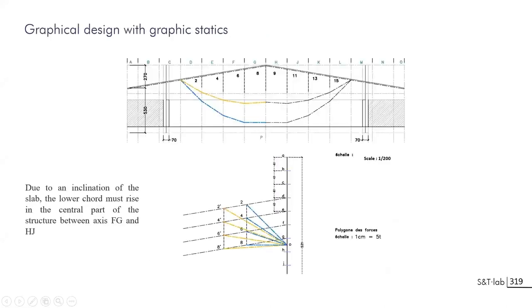So first you want to draw a funicular line. You would like to have a funicular line that would be horizontal in the middle. And if you do so, you have to keep in mind that this funicular line will be equivalent to these two lines of the roof. So you are building a load line in which, from the corresponding letter, you draw parallels to the roof. And you have to connect to the rays that will give you the geometry of the funicular line.